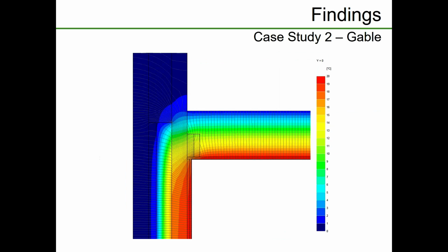You can see here there's a lot of constructional thermal bridging going on. It would help, and you can see it's going predominantly this way as well. So if that insulation was at least to there or even higher, it would reduce that, and at least you'd be going to a warmer airspace, so there'd be less heat flow going that way.